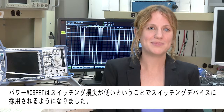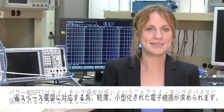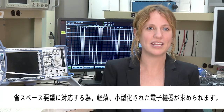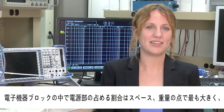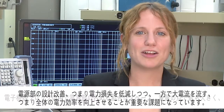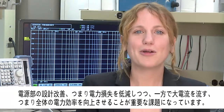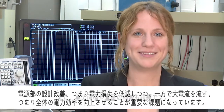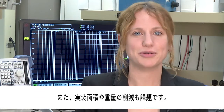The power MOSFET has become the standard choice as the main switching device due to low switching losses. Thinner and smaller electronic devices are becoming more prevalent in consumer electronics. The power supply accounts for a large part of the electronic component blocks in terms of both space and weight. Because it is required for design engineers to improve the overall power supply efficiency, a reduction in power loss while allowing large load currents has become more important. Of course, the required mounting space and the weight always need to be reduced.